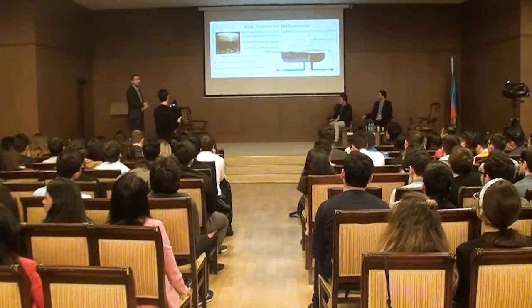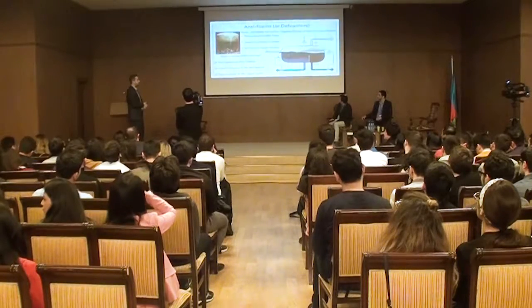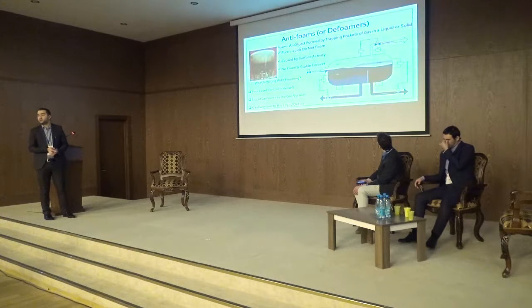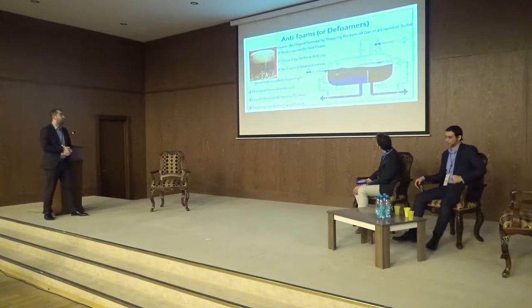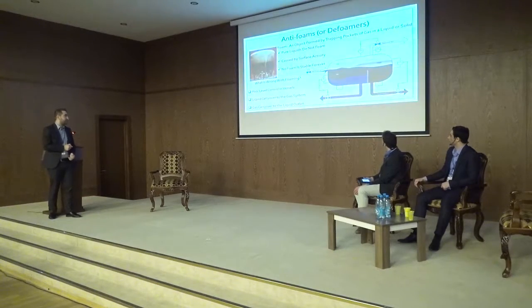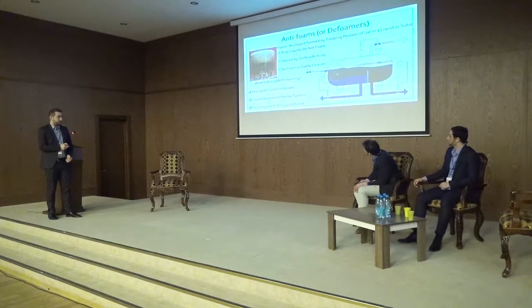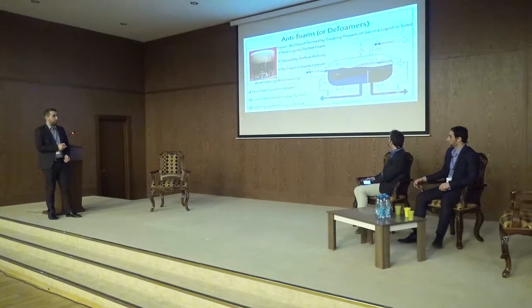I'll move to the antifoams, since the video didn't work well. Antifoams are chemicals that we use to optimize the separation efficiency in the system. So this is what foam is, actually. When you pour an acidified, pressurized fluid or drink into a glass, and if you are not very careful, you may get this. This is something we don't want to have in our process, because in a three-phase separator, the foam can cause too many problems.